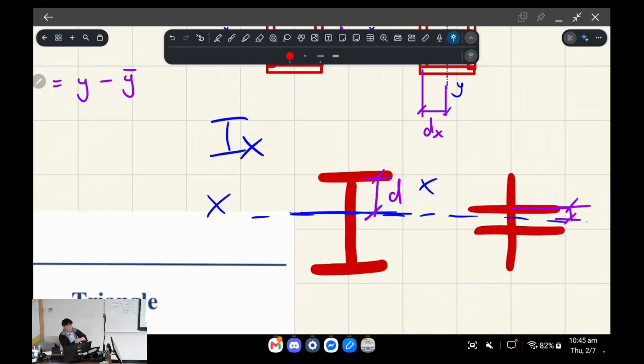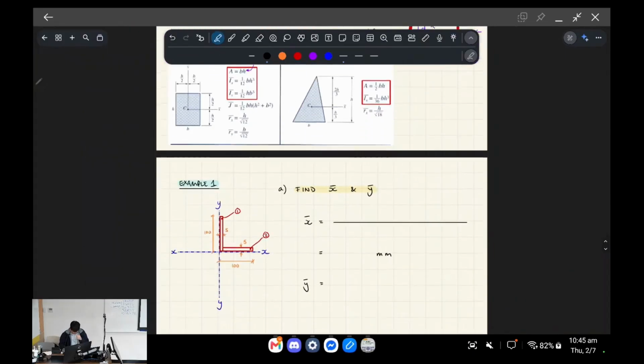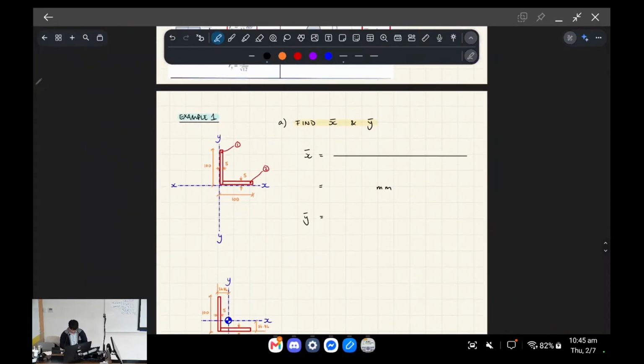So the reason why you see a lot of steel beams in real life is because this is one of the reasons why it's a heavily optimized shape, right? You're putting as much of the meat, I guess, of the cross section as far away from the bending axis as possible, and therefore you're going to give it a higher stiffness. Okay, so you'll see why due to the formulas, but it's easy to see once we do the questions. Okay, so I'm a bit conscious of the time, so I'll try to go relatively quickly.